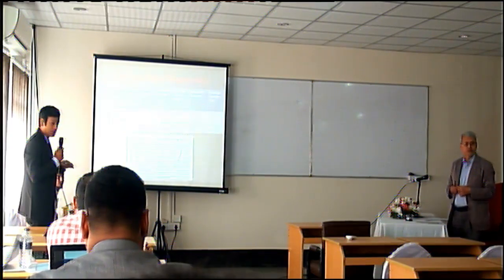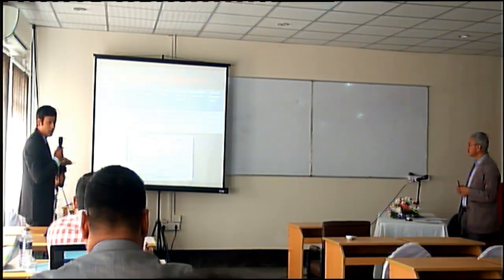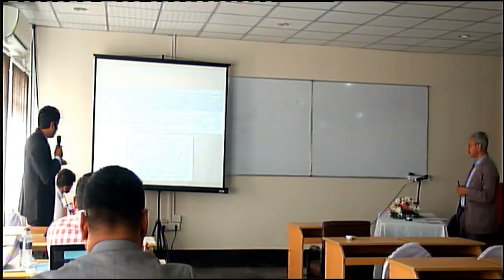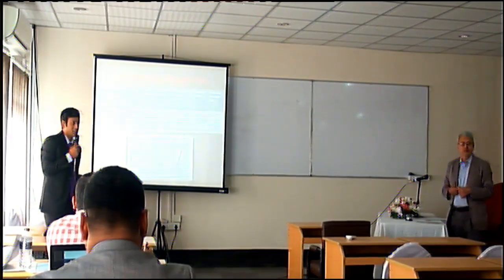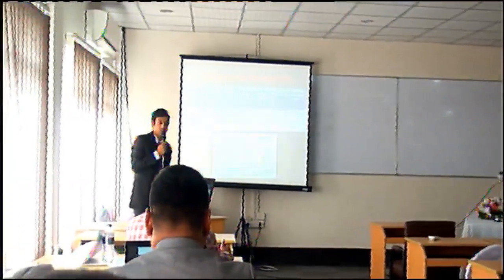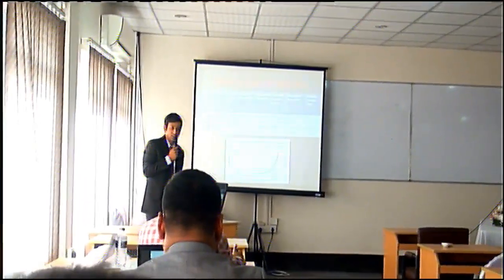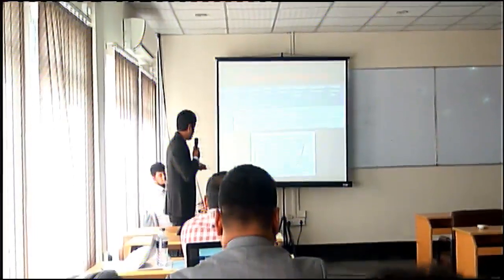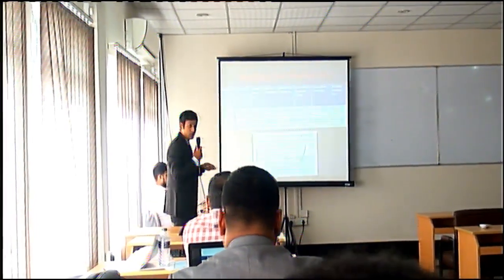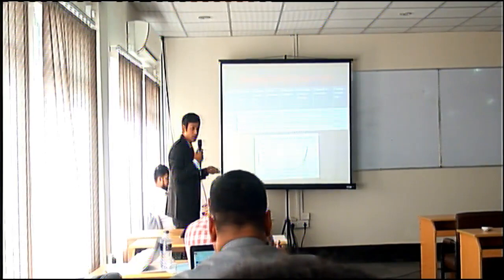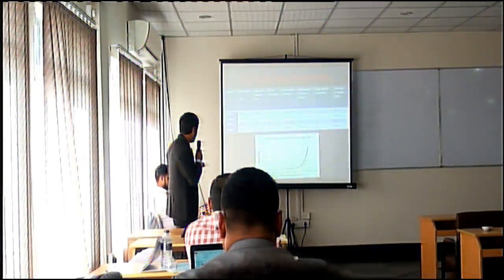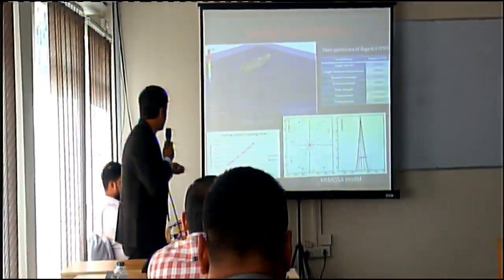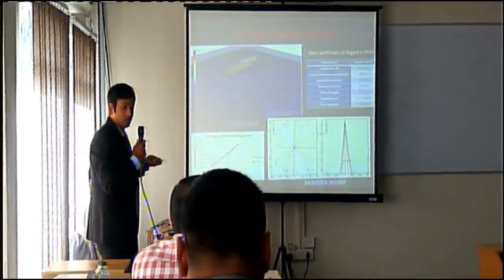How do you make that touchdown point here? From zero, where is the anchor, and is it a conventional anchor? This anchor we have taken just as a fixed point, not calculating that much. But where will be the touchdown point? From this curve, can you get the restoring force? Restoring force by the mooring line. From this curve, is it possible to get? Yes, from this curve we will get the restoring force.